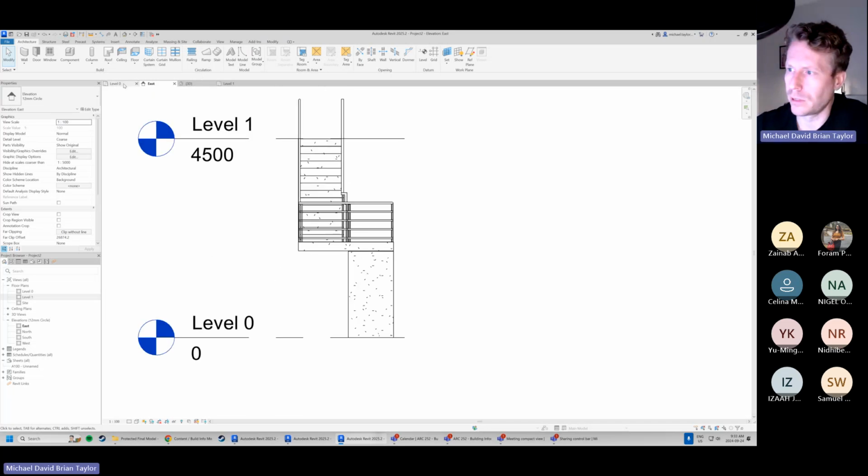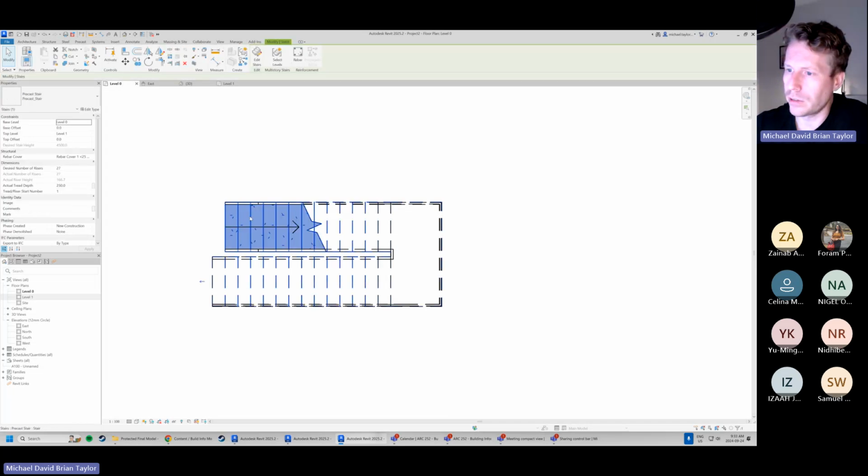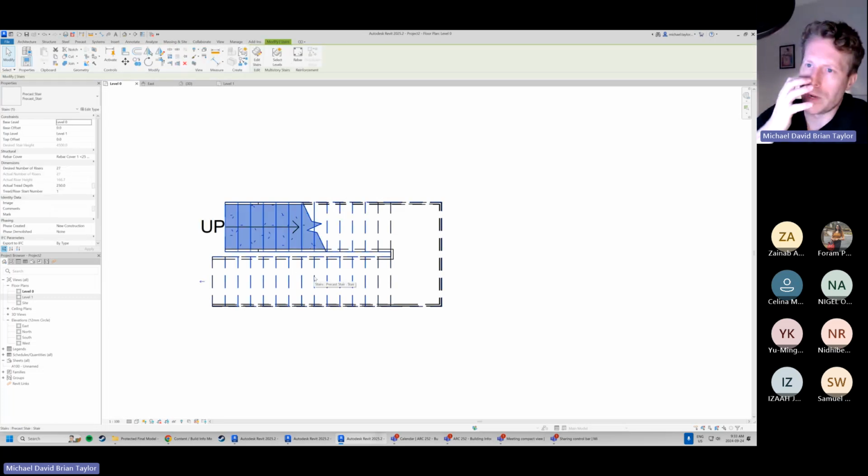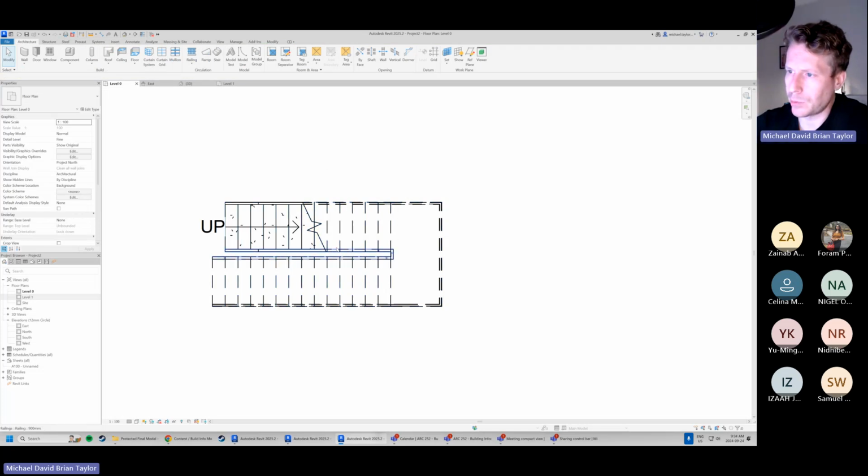Let's jump back to our level 0 here. So if I click on it, you can change certain things. We can change the kind of elevation, starting points and end points of the stair, but we can't change so much else. One thing that maybe you want to change is the overall width of our stair. I actually think we set it at 1,000, so we can change that. But you can see right now we can't change it until we actually go into the edit command. So what we'll do is I clicked off, double tap to escape.